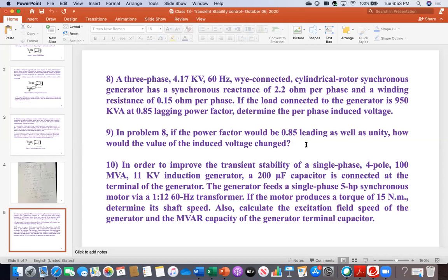Dr. Ali, I got an EA value of 3.34 kilovolt. 3.34. It looks like some different number. In your result, do you have the angle, the phase angle? No, I didn't use that. This means I think that is the problem probably. I mean, in the answer, you can tell only the magnitude, but when you are calculating, definitely there should be an angle. Yeah, it's a three-phase, so there should be the phase angle.